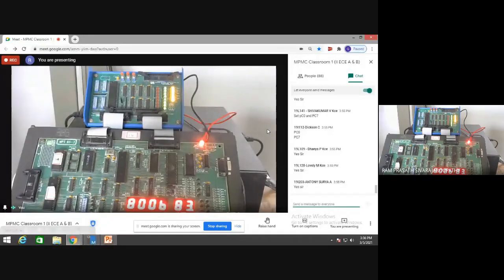Can you people tell the control word to reset PC0? Tell me only the control word to reset PC0. What is the control word to reset PC0? Yes, 00H. So that control word, I write 00 with OUT D3 into the control word register 83H. Again I call the delay program, the set delay, call 0090. Then C3 0480. Let's see what happens when I execute this program.